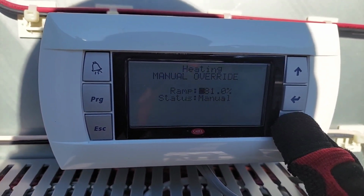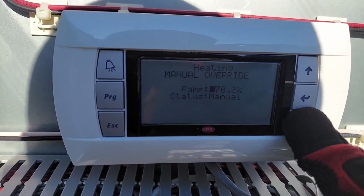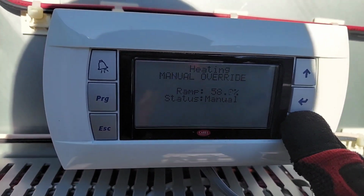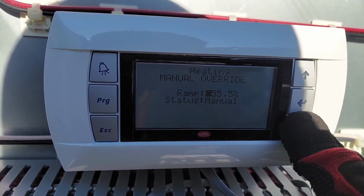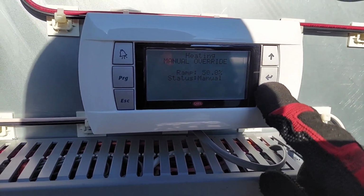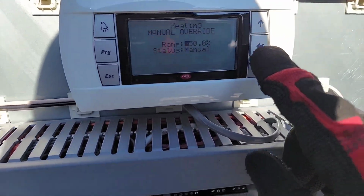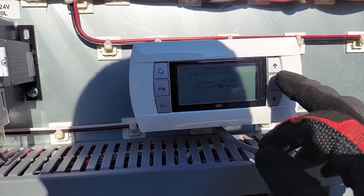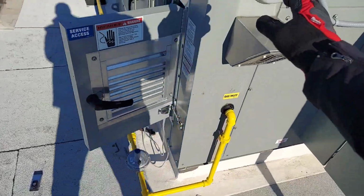Boom. So bring it down to 50%. We could do 75%. Certainly it's going to drop, but I'm curious to see if it's going to go half at 50%, which is low fire. And the burner controller takes care of all of this. This controller, at 50%, sends out 5 volts to the burner controller, and the burner controller does the rest, as far as the low fire, high fire, the gas valve, the modulating part of it, and also the exhaust fan.